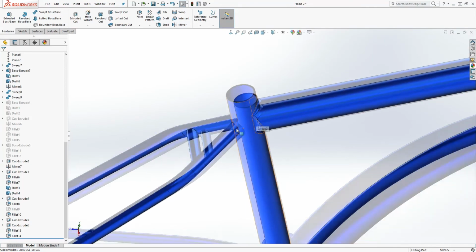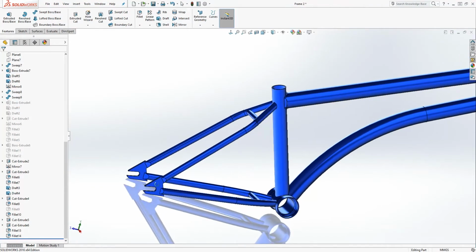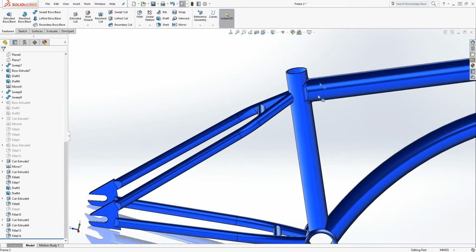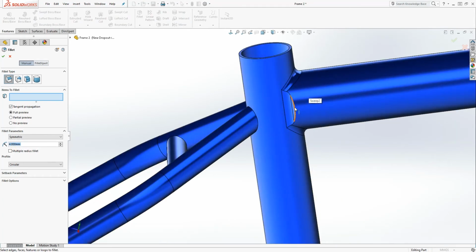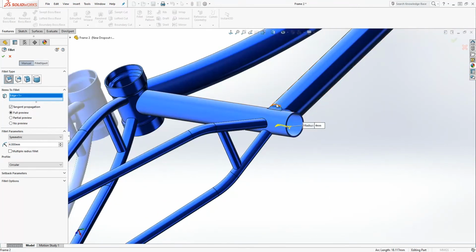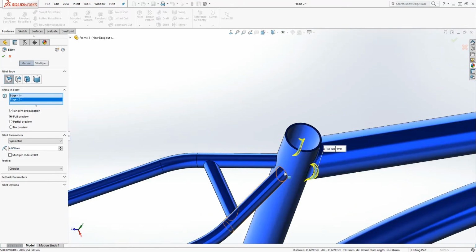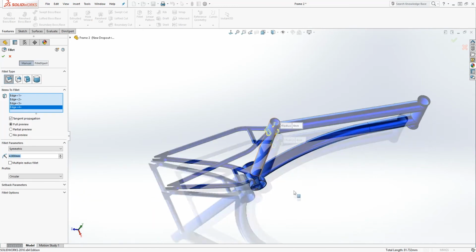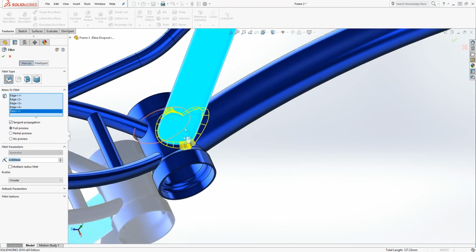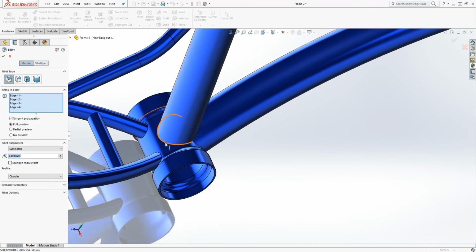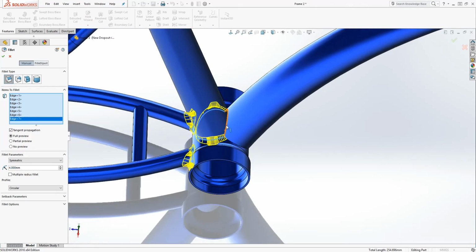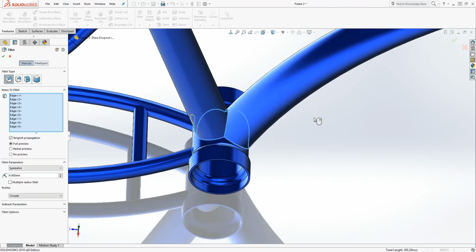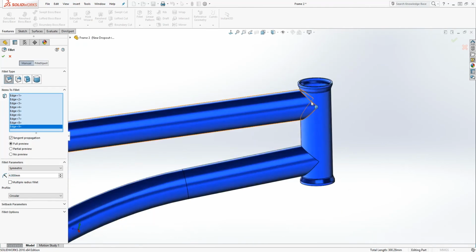And the only thing we need to do is add a fillet to all those places. So let's start with the ones where we suppressed those fillets. So click your fillet and make it 4, and so we want to add it to this face, that face, back here, back there, and down on this edge, that edge, this edge, this edge, and over here.